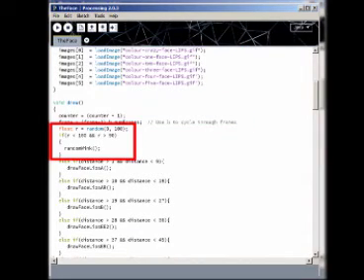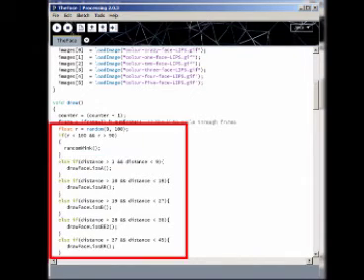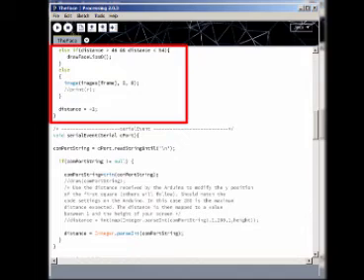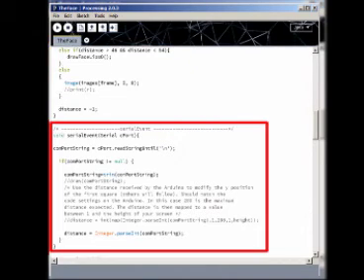The random variable is used to trigger the random wink image and is triggered whenever the number is between 90 and 100. The if-else block sets out when each particular image should be displayed in respect to the distance variable received from the ultrasonic sensor via the Arduino serial port. The serial event method reads the incoming messages from the serial port and converts them to an integer in order to be used in the previous if-else statement block.